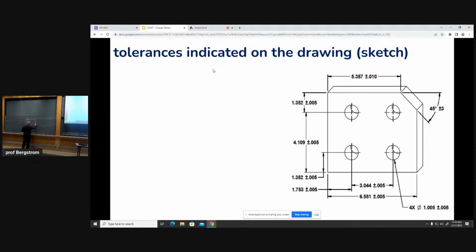What's next? I got two parallel sides because we stuck one side up, faced it, flipped it over, faced it at the right height. Yep. Now, there's also another set of two parallel sides, but one of them is kind of chipped off the corner. Well, this might be bandsaw cut on the edge right now.